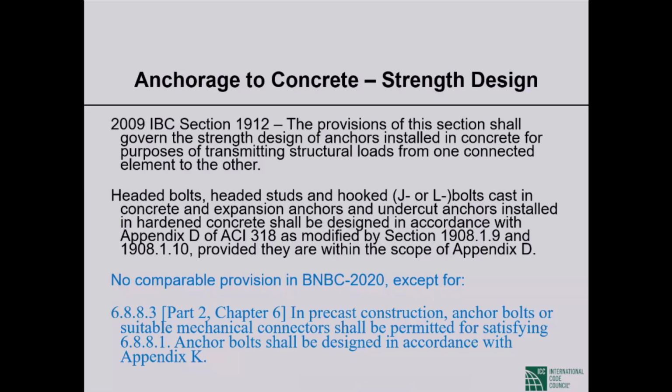Headed bolts, headed studs, and hooked, which can be J or L bolts, excuse me, cast-in concrete, and expansion anchors and undercut anchors installed in hardened concrete shall be designed in accordance with Appendix D of ACI 318 as modified by Section 1908.1.9, etc. So the IBC was sending the user to Appendix D of ACI 318 where the anchor design provisions were.